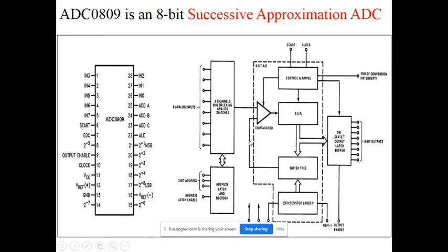Suppose you are doing a project such as a greenhouse or home automation. If you want a maximum of 8 sensors, you can use this controller. But if you want more than 8 sensors, don't use 8051, use something else which has more analog channels. This 8051 uses the 0809 external ADC, which provides 8 analog inputs, so a maximum of 8 sensors can be attached. If your project needs more than 8 analog inputs, don't use 8051 along with the 0809 external ADC.